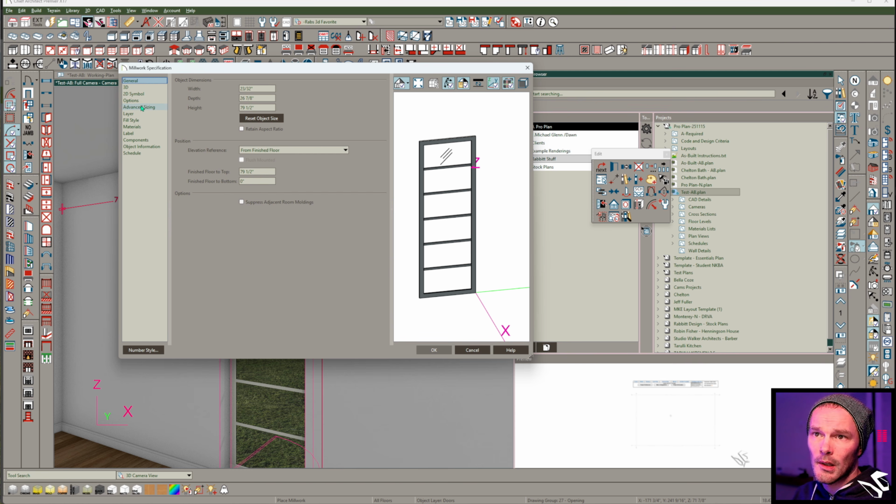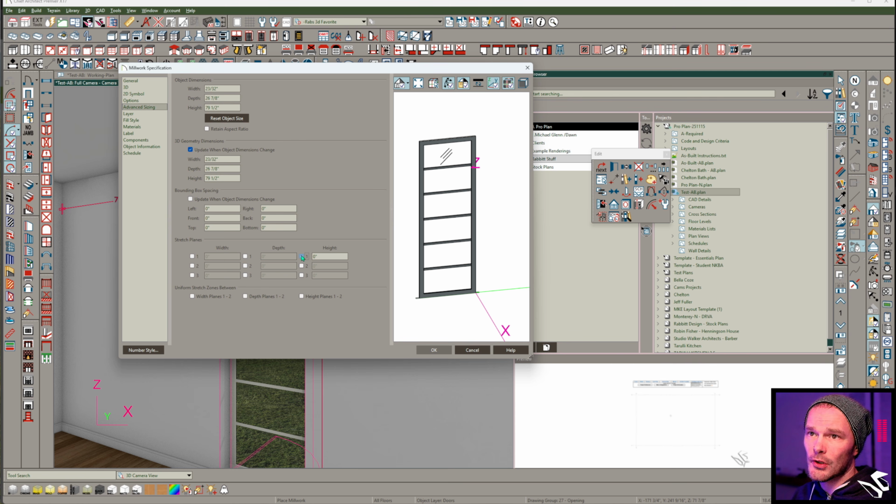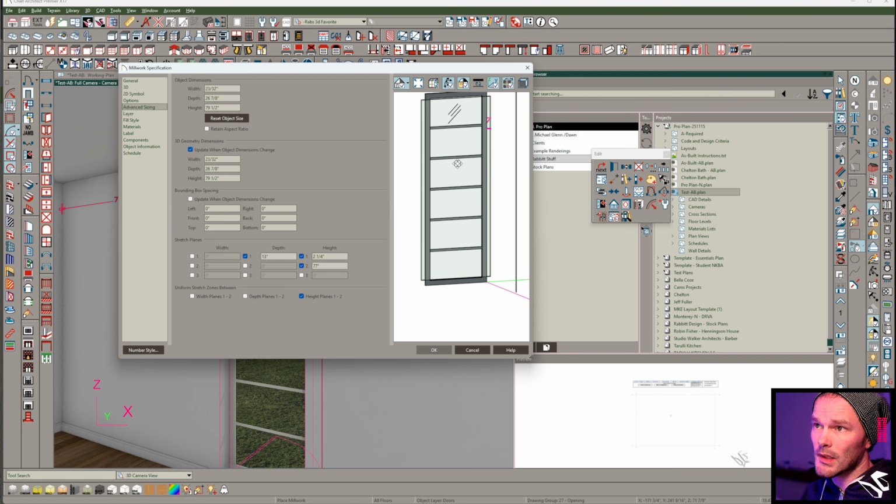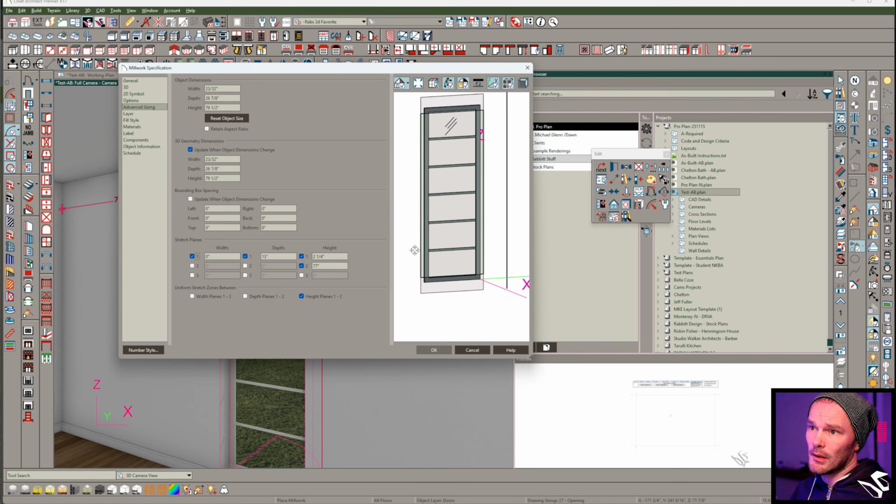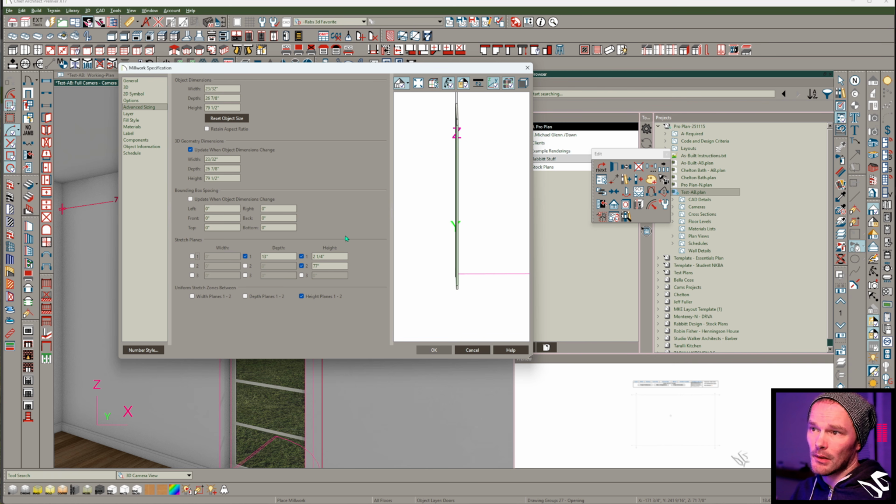That's the point. So get to the advanced sizing panel. Depth for sure, go half of the depth, maybe 13. Oh, I clicked height. Oops, here's depth, 13. Height could be half the height, or it could be 12, or it could be 5. It's probably going to do 3 different ones, or I do uniformly resize in between, which I've got 2-inch rails, so I could just go uniform stretch planes in between. So it's going to uniformly stretch everything, but it won't touch my rails. Perfect. And then width would just do thickness. That's fine. Leave that unchecked.